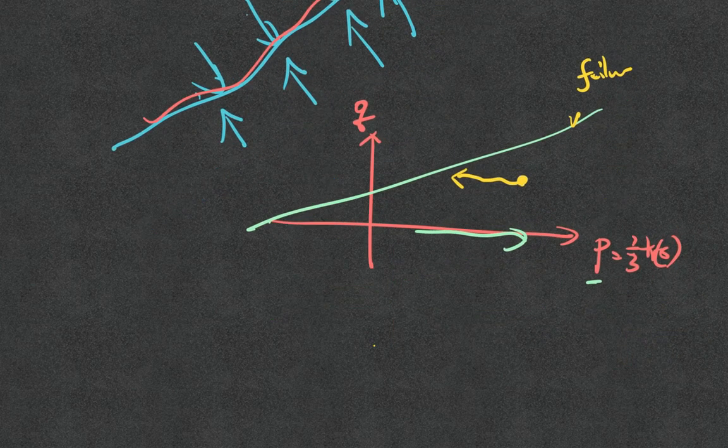So the total pressure is equal to the effective part plus, sorry, let me use consistent notation. The effective pressure is equal to the pressure of the solid, which is a function of the solid part, minus the pore pressure of the fluid.